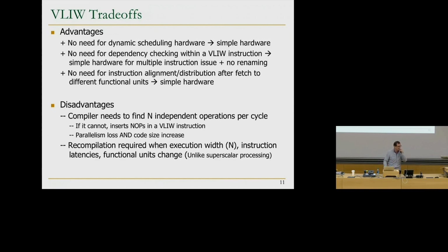Would no operations actually work as just some instructions, like a branch that never does anything? Exactly. It's basically an operation that doesn't do anything. It doesn't change anything, but it just takes that cycle so that no other instruction can go in that cycle. For example, branch-not-equal that looks at the same register twice. That's right. Yes, exactly. You can repurpose some other operations as no operations, as long as you don't have any side effects, you don't change anything in the state.